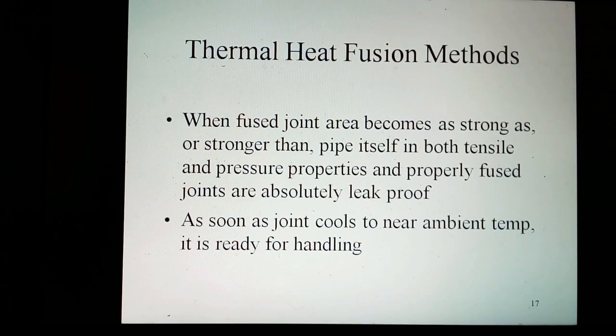When fused according to the pipe and or fitting manufacturer's procedures, the joint area becomes as strong as, or stronger than, the pipe itself in both tensile and pressure properties, and properly fused joints are absolutely leak-proof. As soon as the joint cools to near ambient temperature, it is ready for handling.